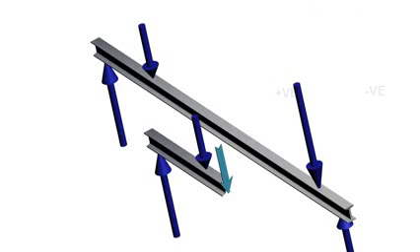So just by applying force balance in vertical direction on the free body diagram, we can determine the value of shear force at a particular cross-section. Now we can apply the same concept in different cross-sections and find how shear force varies along the length of the beam.